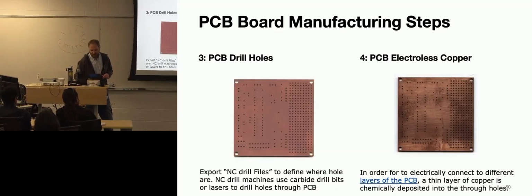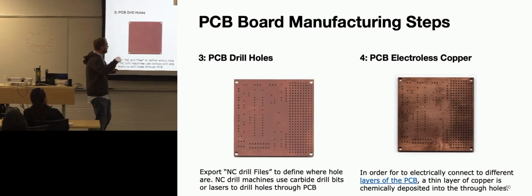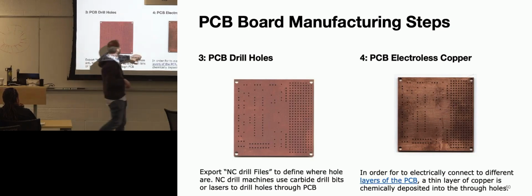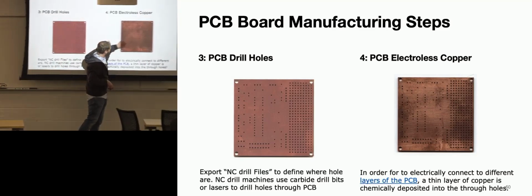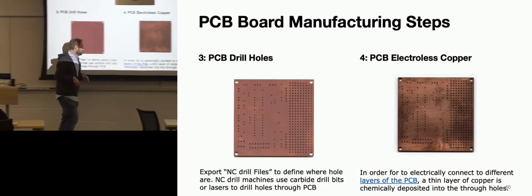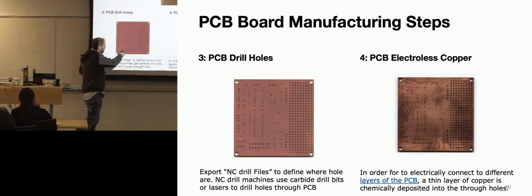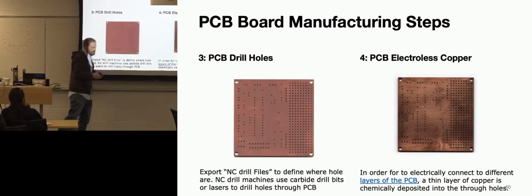Okay. Then they're going to go through and drill holes through everything on here, right? Let's see, what are they going to do? And then they're going to electroplate, I don't know. They're going to plate the copper. Yeah, they're going to try and plate the holes. They're trying to connect the holes from the top to the bottom where they're supposed to.